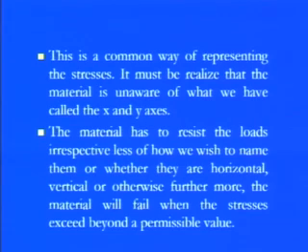So this is a common way of representing the stresses for the xy plane component. If we were considering 3 dimensions, then as I told you, we would need to consider all 9 components, the triaxial form, in which all 3 axes are mutually perpendicular. But here we are only considering the 2 axes x and y, where these 3 stresses are there because of the symmetricity of the object. It is pretty easy to describe the whole state of stress using these stresses.